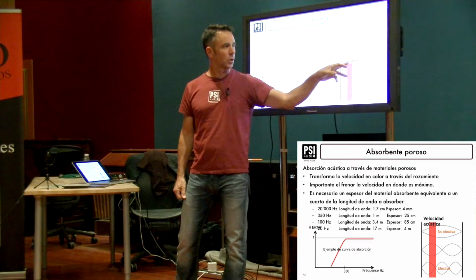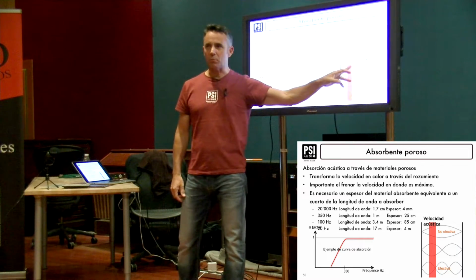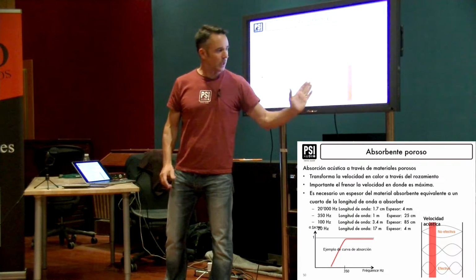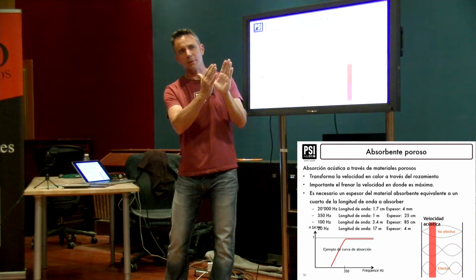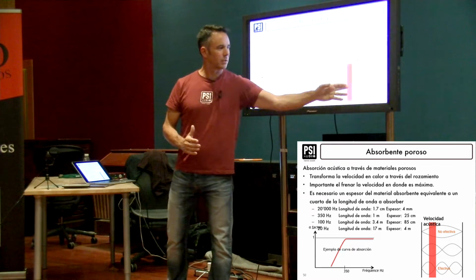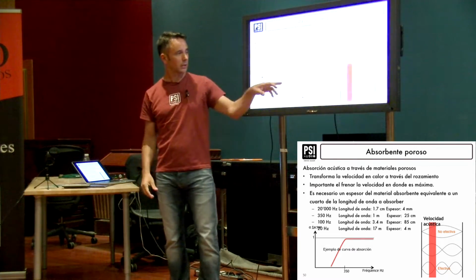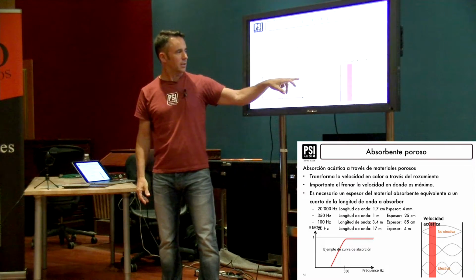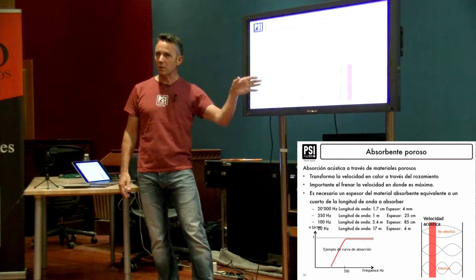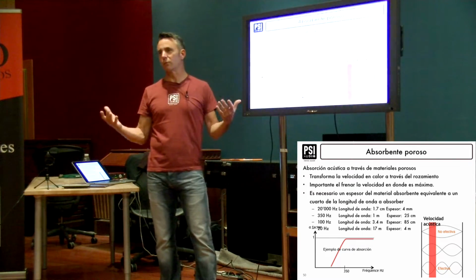So typically, a quarter of the wavelength of the frequency away from the wall, which for the first room mode is in the middle of the room, by the way. That's a bit disturbing. But anyway, you need either to position the porous material off the wall, or you can have it thicker. When you buy any porous material, rock wool or anything like this, of different thicknesses, it'll work very well, and then below a certain frequency the efficiency is going to drop down. Typically this is around a quarter of the wavelength of the frequency you want to absorb.